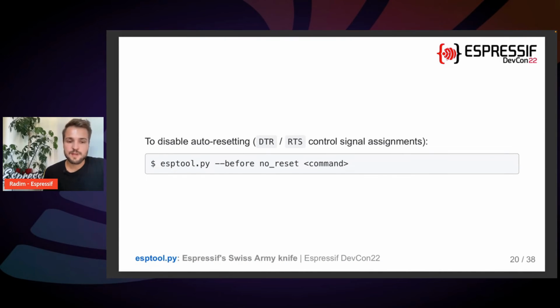This behavior, this auto reset behavior, can actually be disabled just by supplying the --before no_reset argument to esptool. This might be helpful in some cases or in production environment.